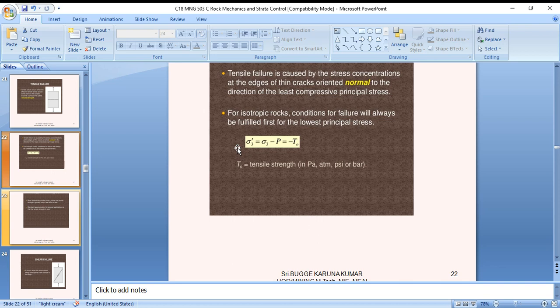For example, in sedimentary and foliated rocks, the tensile and flexural strength and modulus of elasticity are generally lower in the direction perpendicular to the bedding and foliation than in the direction parallel to the bedding. In some instances, these differences are large enough that their effects should be considered in evaluating a rock structure problem. However, very little is known about the anisotropic property of in situ rock. In fact, data are available only on the anisotropic property of laboratory-size specimens.